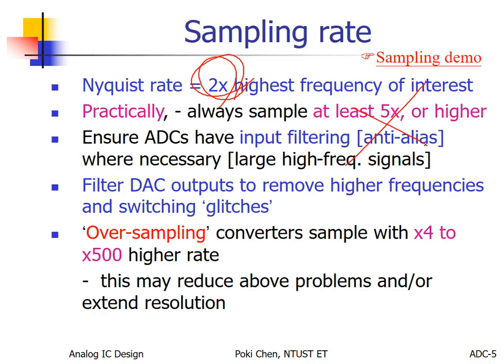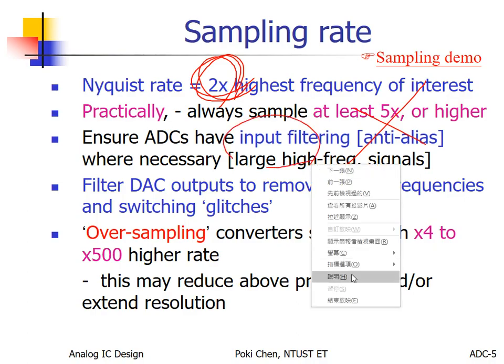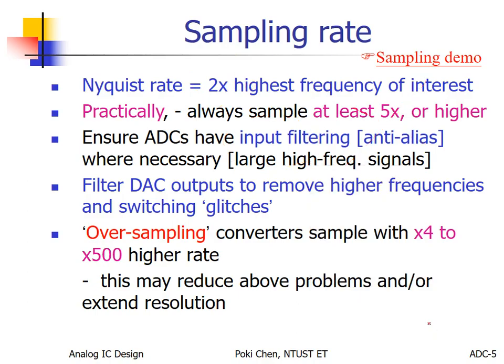Because on chip we can match the devices, I mean critical devices. Then we can achieve higher-order low-pass filtering even in the analog domain. So right now I think a little bit larger than 2 times the highest input frequency should be good enough. Here, for the low-pass filtering, sometimes we call it anti-alias, because you want to prevent this error, so we call it the anti-alias filter.